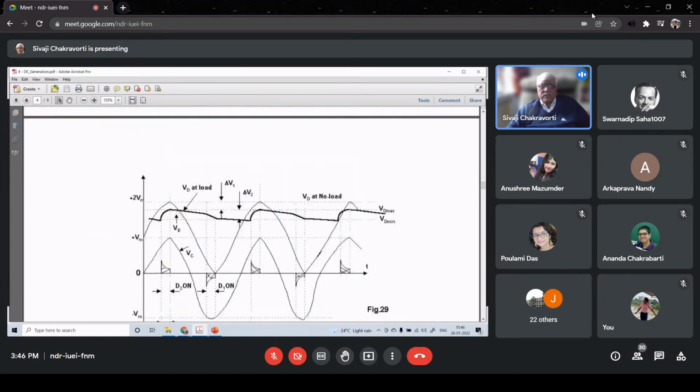And there is a second voltage difference, del V2, which is the highest value across C2 to the lowest value across C2, and that is because of the discharging of C2. So del V1 effectively comes because of charge loss of C1 over the reverse resistance of D1 and also through D2. Del V2 is purely due to the discharge of C2.